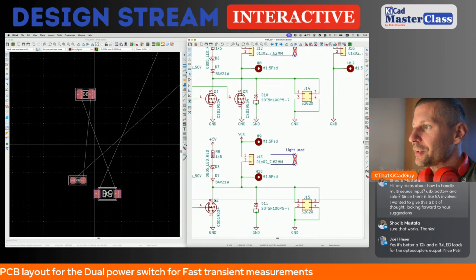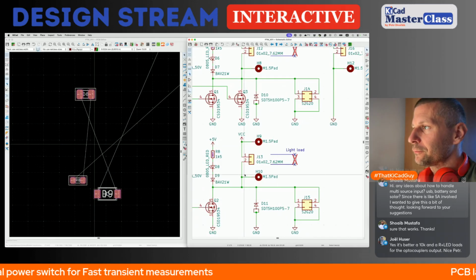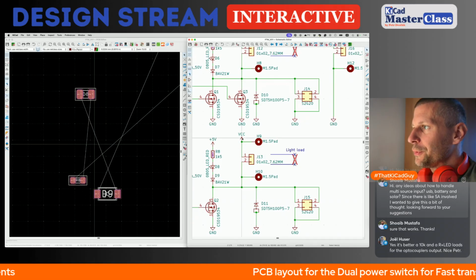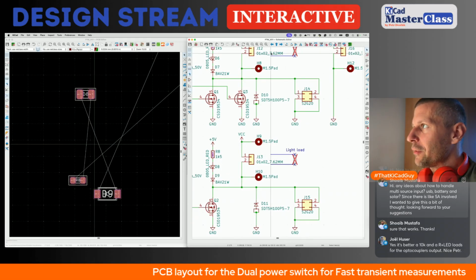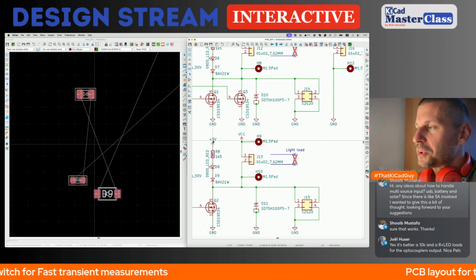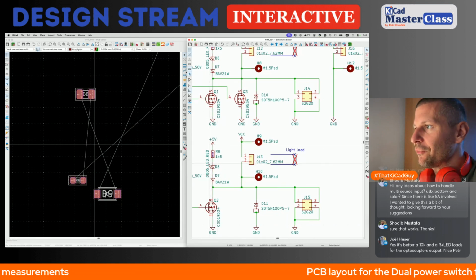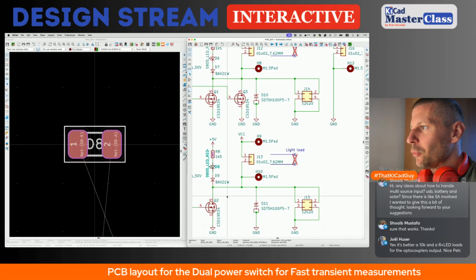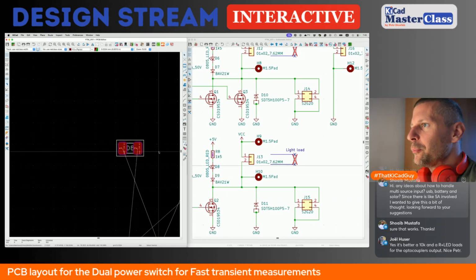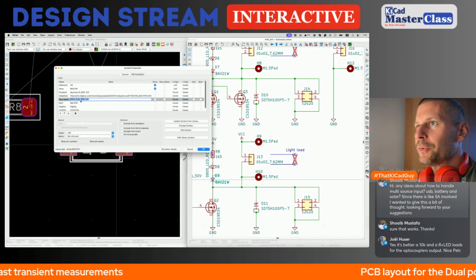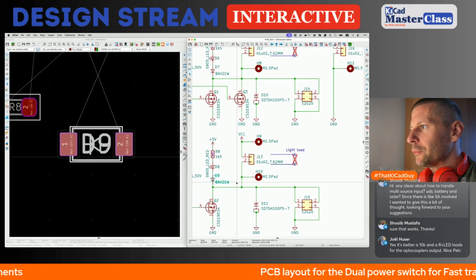So when the transistor is switched off, current would flow from the load through the light or heavy load resistor through the LED to the 5 volt auxiliary power supply. It means that 95 volts would be the reverse voltage of this LED, so the LED would definitely go away in a millisecond. So here is the 200 volt, 250 actually, protection diode for this LED.